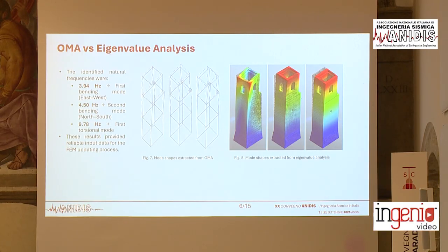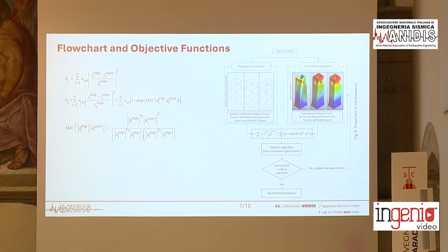As you can see, the first and second modes are bending modes along the east-west and north-south directions respectively, and the third mode was a torsional mode.